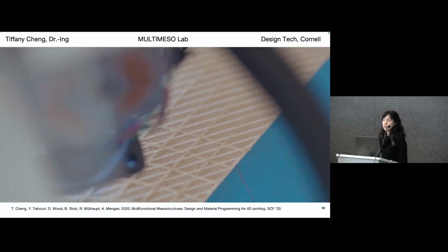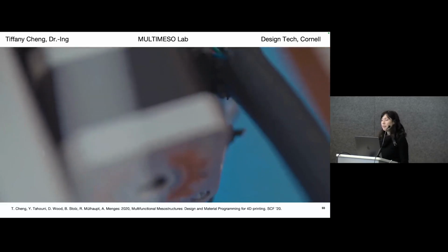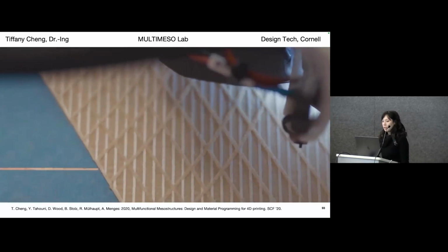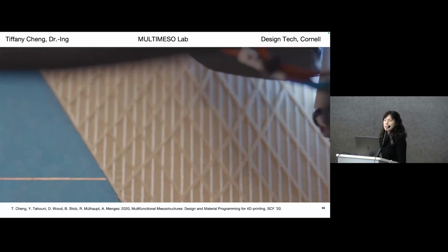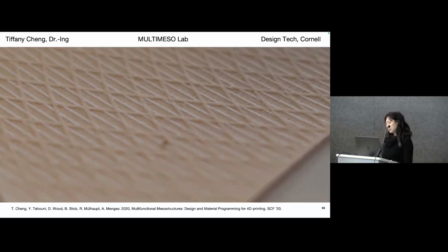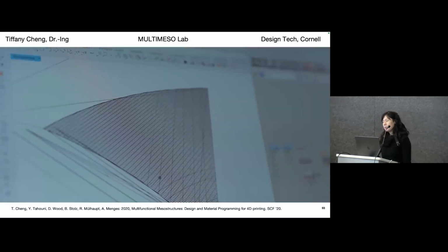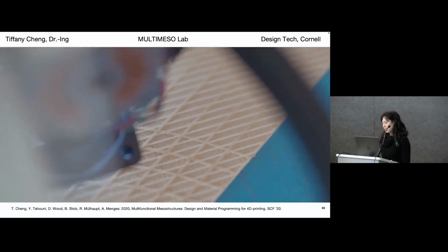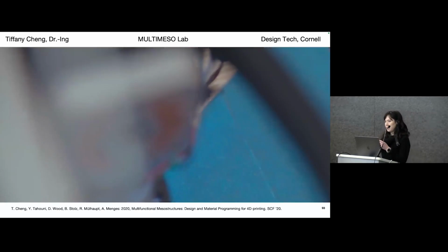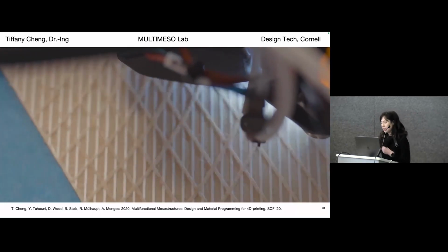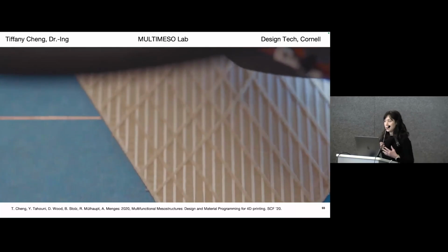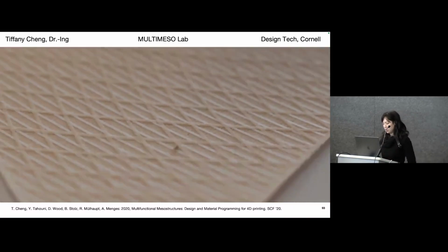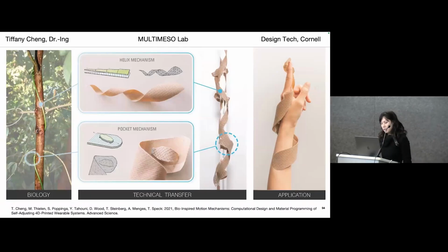And here you're seeing filament fabrication, which is a very affordable and accessible technology. So, different than how you might traditionally use 3D printing, we control the actual extrusion process of that technology using computational design. And that helps us control the material properties directionally and control things like directional stiffness and areas that change shape. So if you look to nature, we can actually design better products and solutions.